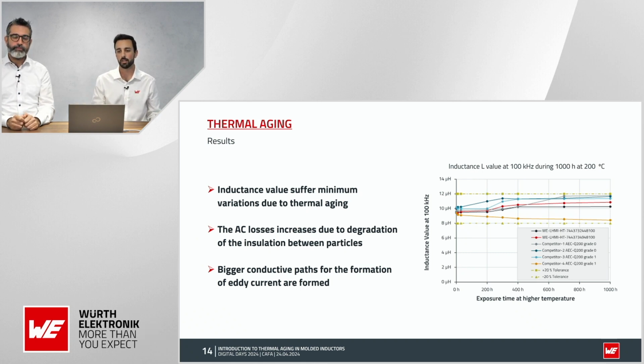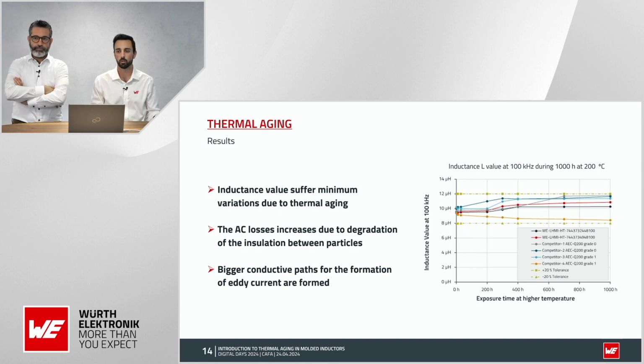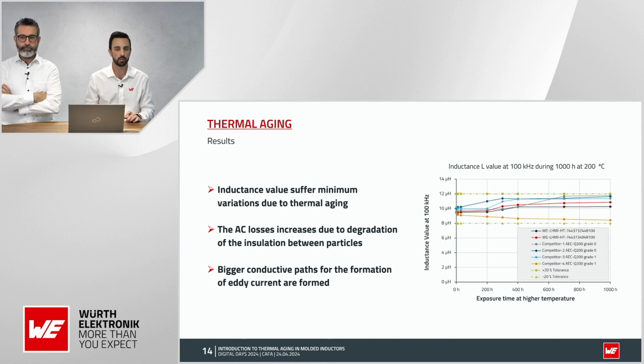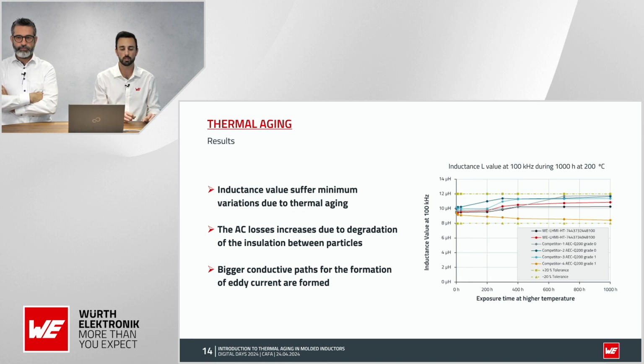Here we have an example of a comparison of testing we did between two newly released parts for the industry portfolio, two LHMI high temperature ones, as you can see in black and red, and other competitors we selected from the market, qualified grade 0 up to 125 degrees, but also grade 1, 150 degrees. And we periodically measure the evolution of the inductance against time at 200 degrees.